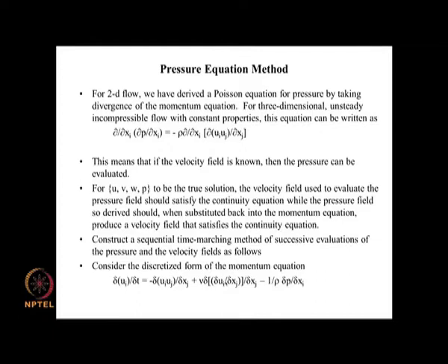These dels here are difference operators. Okay, you could be using upwind scheme here, you could be using the central scheme for this, or whatever other scheme that you want to put here. Okay, so it does not matter what it is. You choose the appropriate ones for the discretization operators for each of these.